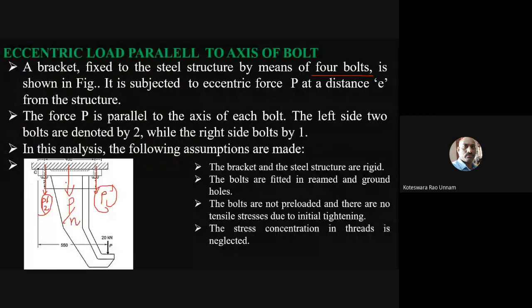In any case, whether the eccentric load is parallel to the axis of the bolt, or perpendicular to the axis of the bolt, or even the first case, the load is equally shared by all the bolts. You need to consider the total number of bolts, not the total number of sets of bolts. The number of sets only comes into the picture in the case of a bending load or bending stress.